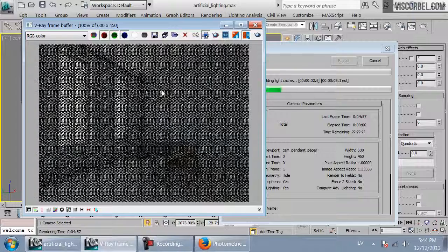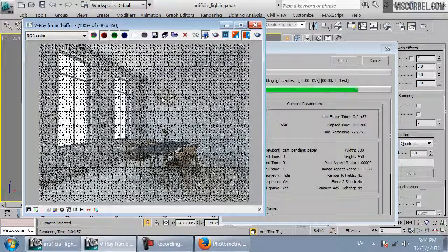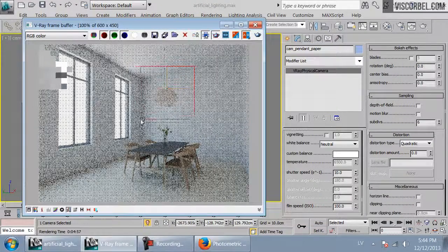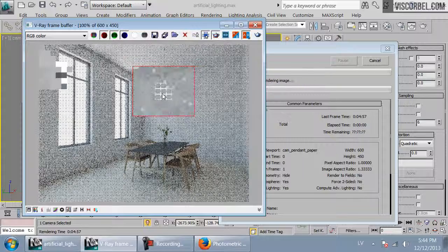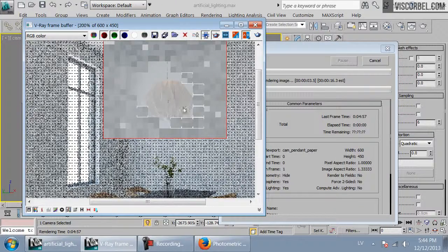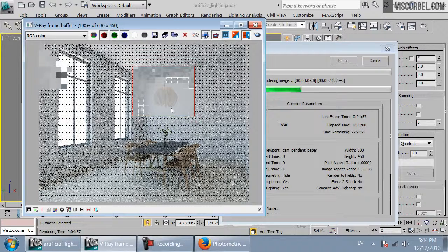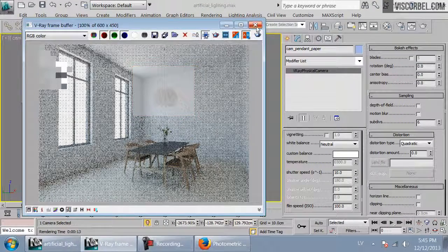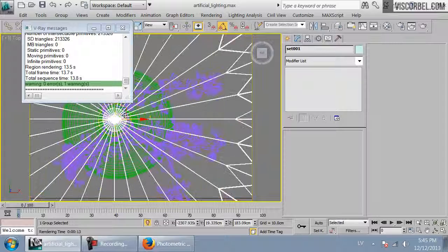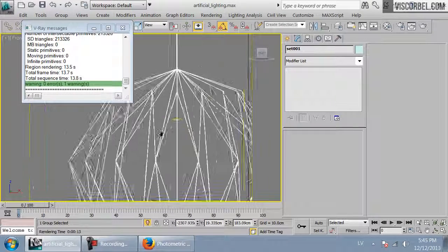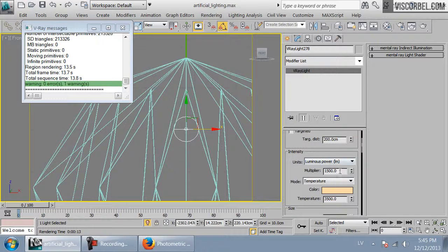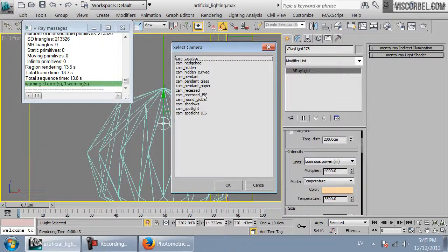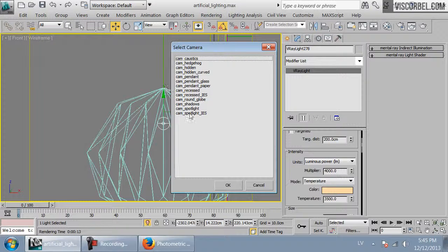And as you can see, our paper lamp is quite dark. And this is a common problem with daylight scenes where you want to turn on the artificial lighting and still make it visible or make it interesting. And this is a problem in real life as well. So professional interior photographers usually carry with them some halogen light bulbs with high lumen output. For example, something like 3,000 to 5,000 lumens would not be uncommon. I wouldn't go higher than that, but you can easily try something like 4,000 lumens, and it should still be realistic compared to professional interior photography.